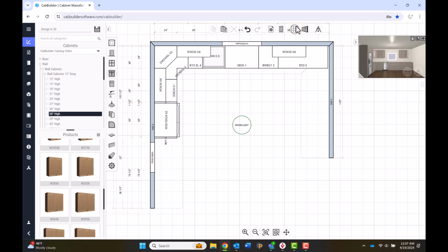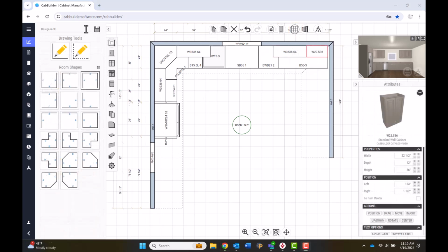Then, to return to the design view, click the plan icon at the top of the elevation view shaped like a design grid. When your perimeter components are in place, you are ready to create an island if the design calls for it. To create an island, you will need a foundation in order to create elevation views and have wall placement zones for easy item placement. For the island, instead of using a solid wall, we will need a construction line, which is a zero-width invisible wall that will automatically create both the inside and outside wall zones for easy item placement on either side of the construction line. Navigate to the top icon along the right side of the left panel.